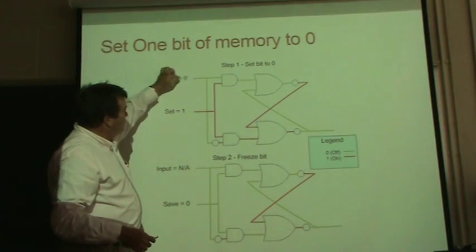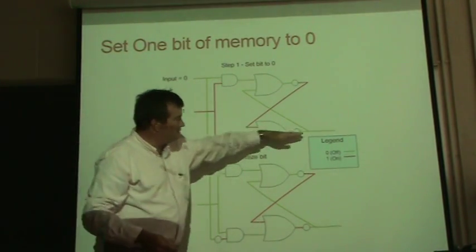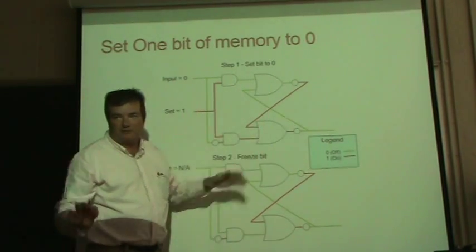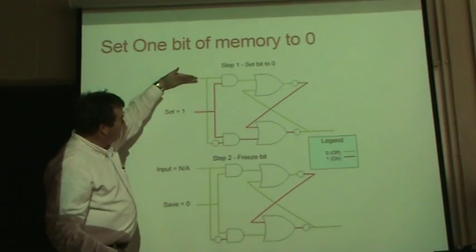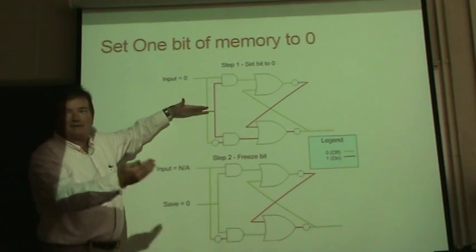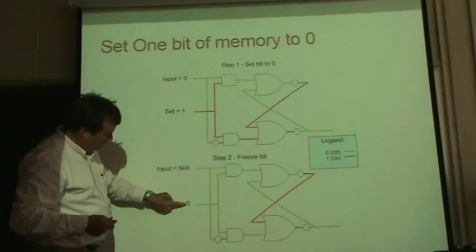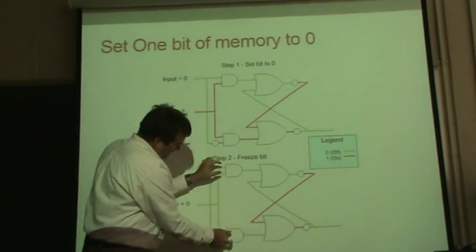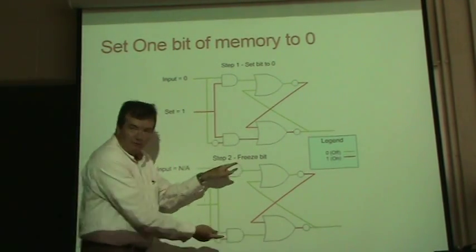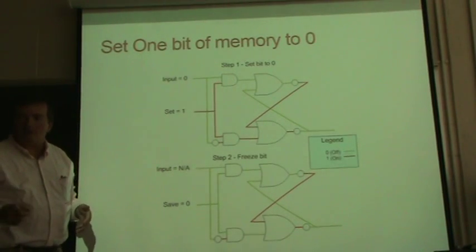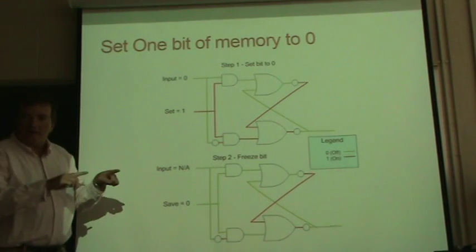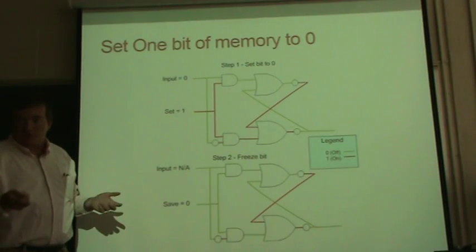And if we started changing to 1 and 0, this thing's going to start a little bit later, changing too. But if we set this to 0, and we set this to 1, meaning accept input, then later on set this one to 0, this 0 going through these 2 AND gates shuts off both AND gates and we have zeros going in. And what we said was zeros going in means the value froze.